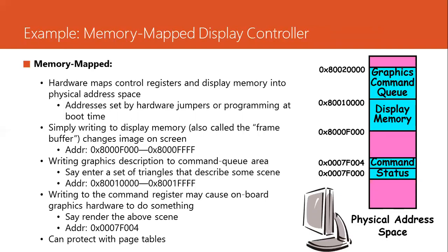So you might be thinking that the controller has to go to the main memory to get the information that needs to be displayed on the screen, which would have been very slow, right? In reality, the CPU writes to an address, and that address is mapped to the hardware of the device. That address comes through the memory bus. The bus adapter attached to this bus recognizes the address and goes directly to the device and never goes to the memory.